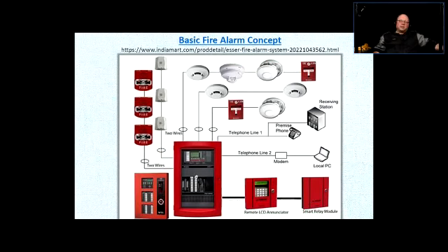Different brands offer different setups, okay, but the basics are the same. You get a main panel and the things connected to it, and by those things I mean annunciators, which would be a noisemaker and a strobe light. Depending on where you are, it is usually required that a certain level of noise is annunciated across the whole building, and a strobe light is associated with that.